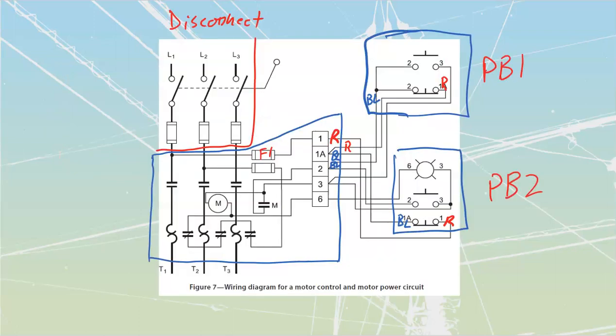What I will often do as well, because at this point we're starting to get a little bit complex, is I'm going to use my Sharpie and I'm going to tick. I just make a little tick line on a wire once I've actually accounted for it inside of here. Just so that later on I'm not going to be like, oh, did I trace this one out or not? I've seen control cabinets that are probably 16 feet long by 8 feet high. I've been inside of those. You just have to keep track because there's 1,000,001 wires that are going to be inside of there.